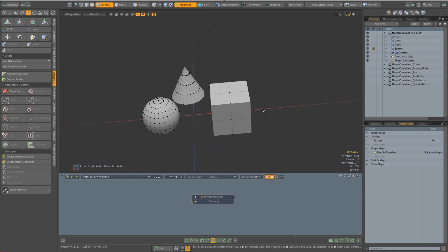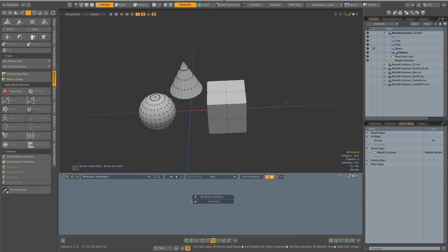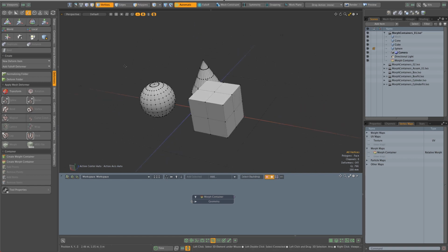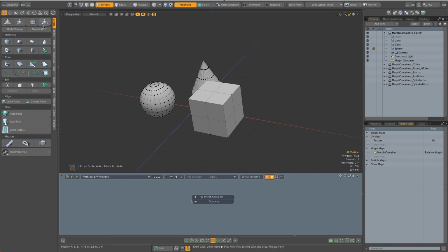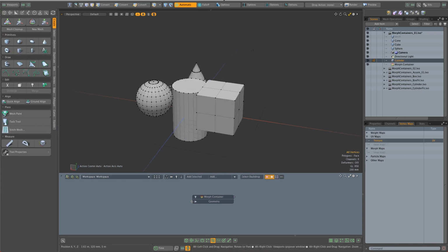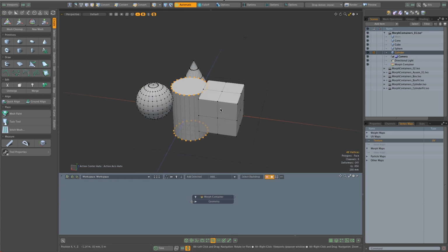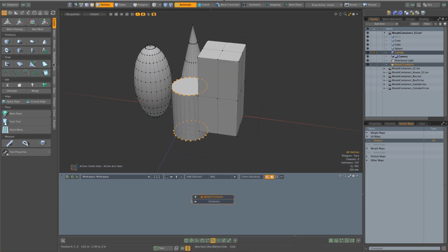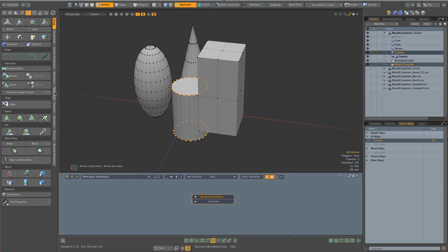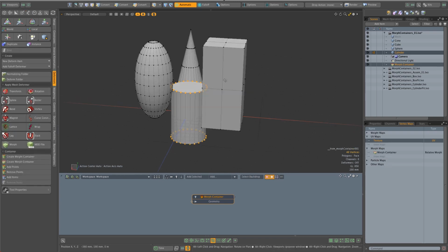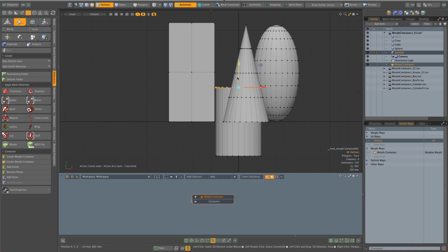You can imagine, even just as a modeling tool, I could have all these morph containers in my scene ready to go. And if I add more geometry into the scene, let's add a cylinder. I really want to add this to my morph container, so I go into my vertex mode, grab this, select my morph container, go back to our setup deformers and hit add points. And there you go. Now I have a morph map in here.